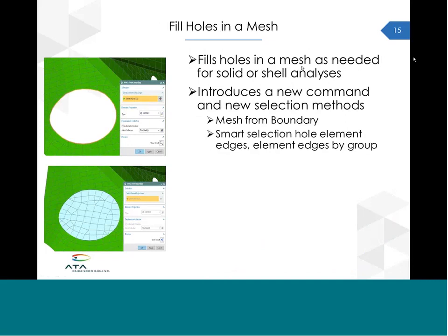The next command I'll show you is the command to fill holes in a mesh. Now this command is actually called mesh from boundary, and the use case here may be that you have existing mesh but no underlying geometry, or maybe you do have the geometry but all you want to do is fill a hole in the mesh. Maybe there's a hole or a cutout or a slot or a notch or something along those lines, and you're really just interested in filling that hole with elements without going all the way back to the geometry and doing a substantial remeshing effort. And this command is very straightforward.